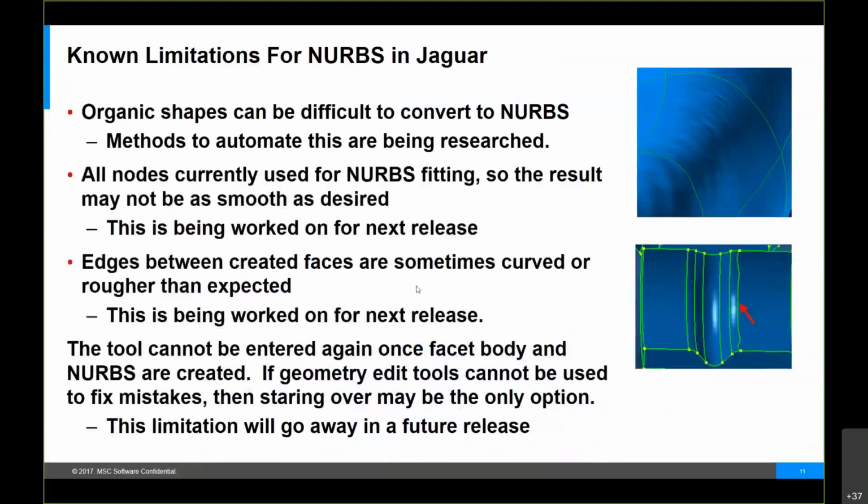Other limitations that we have with NURBS creation. So it's a very, very first version of NURBS. We have two main limitations. These aren't really significant, especially applied to, once again, these faces that are for organic modeling. One of them is that if my mesh is not really, really smooth, that came from optimization. Now, typically they come from models that are very, very coarse from the way the optimization happened. There's a smoothing that's applied, but smoothing is not perfect.